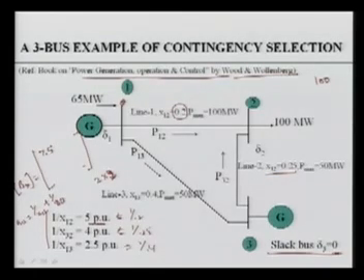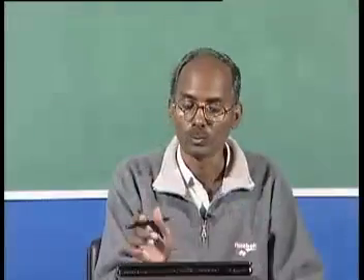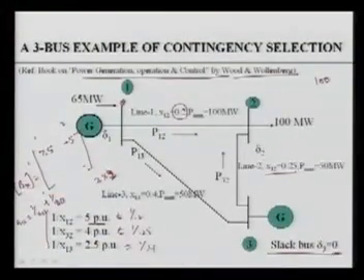Now this off diagonal of this first element means we are talking about 1, 1. Now I am going for this, your 1, 2. So this is your 1, 1. 1, 2 is, as I said, the negative of the admittance between 1 and 2. The 1 and 2 admittance is 5, because here 1 upon x12 is 5. So it is a minus 5 matrix.